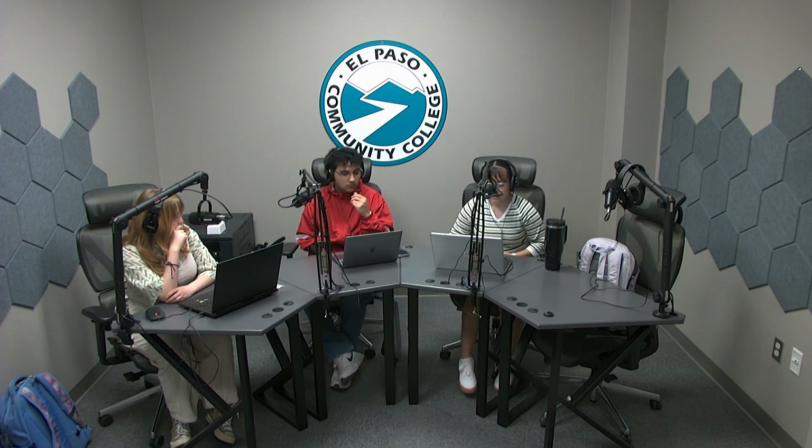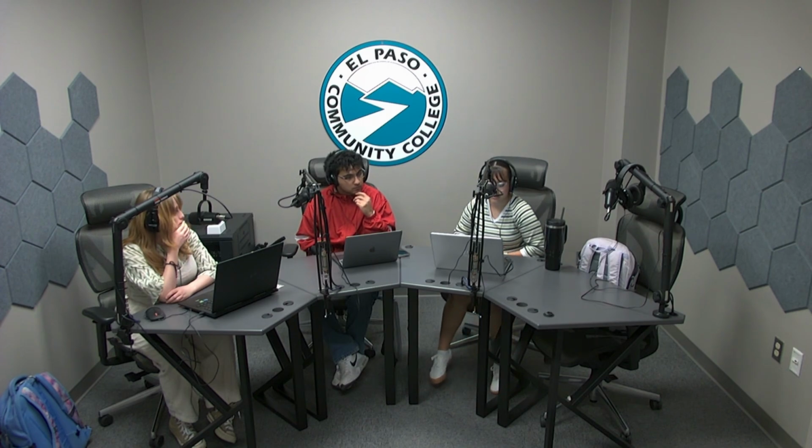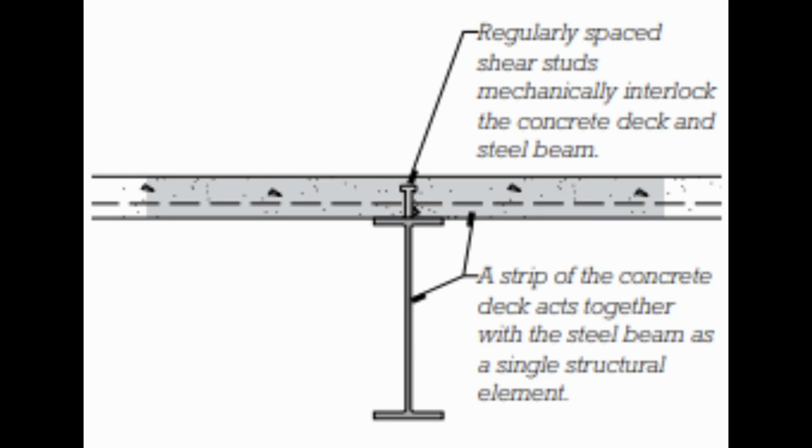They also mention composite beam construction, where concrete is poured on metal deck and shear studs that are welded a few inches apart to the top of each beam, using a specific electric welding gun.